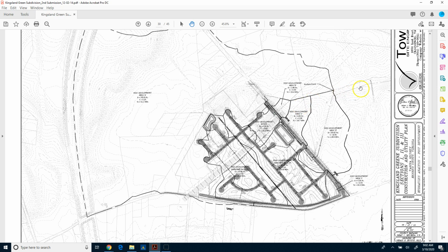because what happens then is you get downstream erosion. So if all this water that would have normally gone into the soil or would have evaporated is now all of a sudden being channeled off the site into a stream, then it may cause erosion down on a neighboring property. So to avoid that, they put in these measures, and you have to go through this hydraulic calculation.